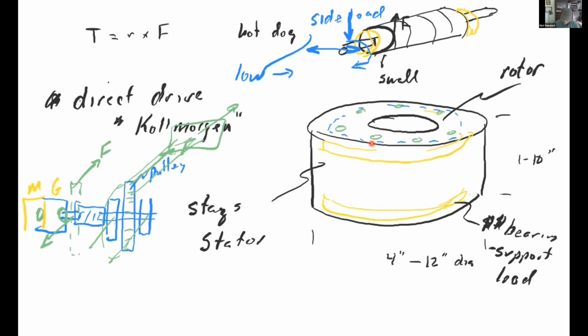It's one of the only few places that you can get high volume, but this bearing can support loads. It can support loads, and they give you tapped holes around the outside, so you can bolt the load right to it. It's a high inertia, relatively, so when you get later into control issues, which I'll describe in motor sizing, you don't have problems with near as much.